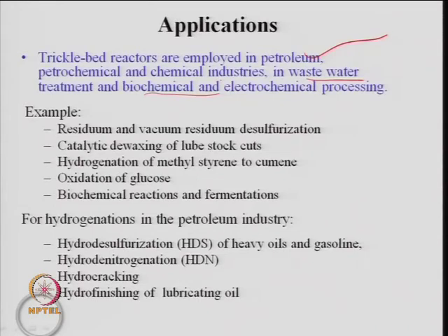So, it is a kind of trickle bed reactor. So, that is an advanced oxidation process, removal of organic compounds like phenol. That is done by the wet air oxidation process, and these are mainly mass transfer controlled processes. So, there also the trickle bed reactor is used. Some of the examples mentioned here are residuum and vacuum residuum desulfurization.